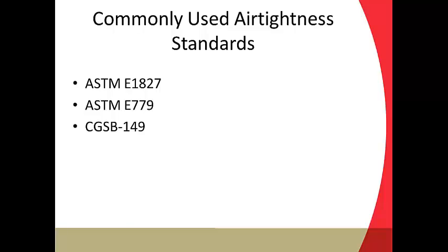All of these standards do require a density correction, so the reading on your DG700 is not corrected for temperature difference between inside and outside the building, and the altitude. So some standards just require a temperature correction, and others require temperature and altitude corrections.